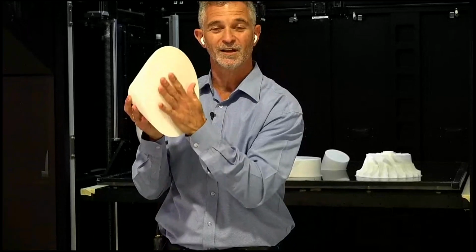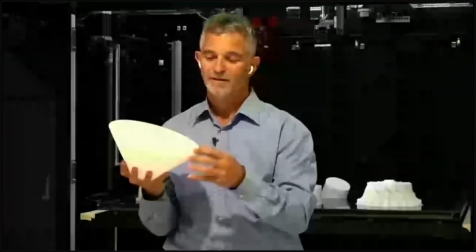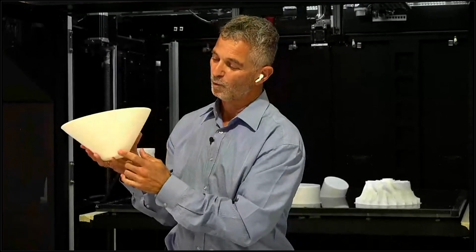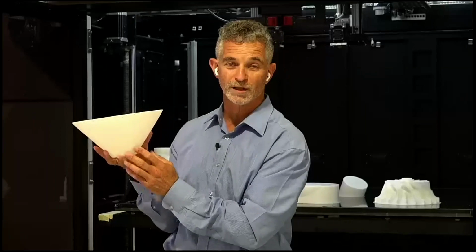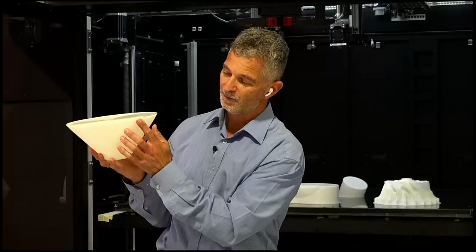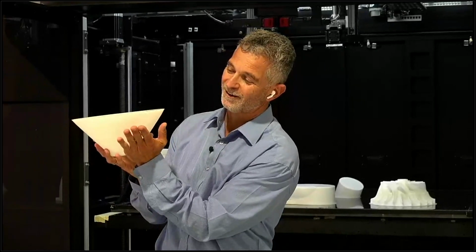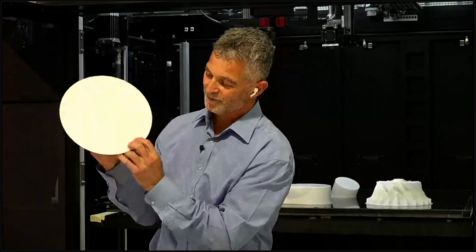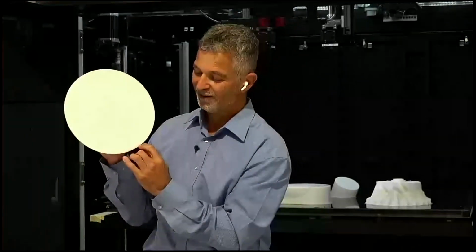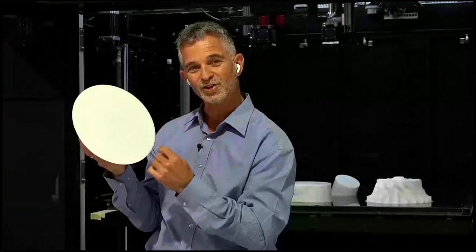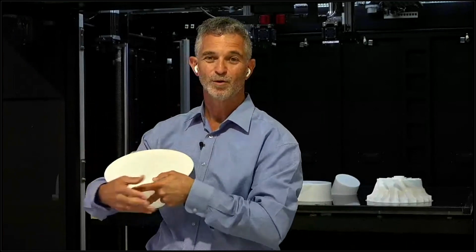For us, we print it this way. First of all, we have a wide angle that we can print because we cure the lines immediately. We can come to a very narrow angle. And once we have the line here, we catch the next line next to it immediately with the UV light.